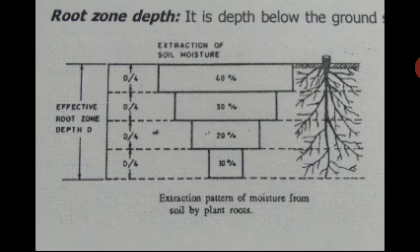At the permanent wilting point, the films of water around the soil particles are held so tightly that the plant roots cannot extract enough moisture at sufficiently rapid rate to satisfy transpiration requirement, thus resulting in the wilting of the plants. It is expressed as the weight of the moisture held by the soil per unit weight of the dry soil.